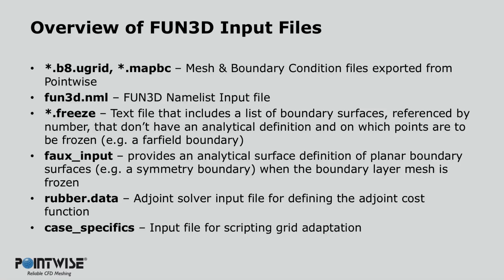The f3d script also allows automating the mesh adaptation process, from setting up the directory structure, maintaining an up-to-date set of run files for each adaptation cycle, running the flow and adjoint solvers, calculating the error estimate for the objective function, and then adapting the mesh accordingly.